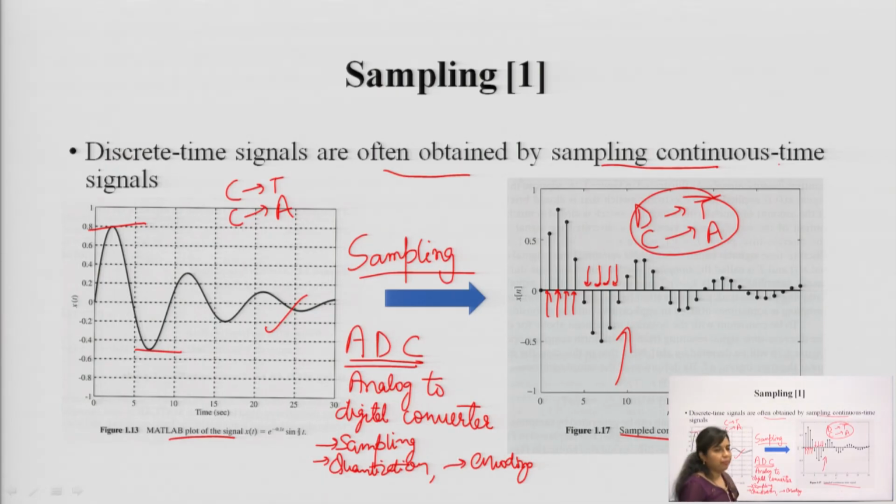Now, there are different types of samplers available, like the sample and hold circuit. Natural sampling, flat top sampling, and ideal sampling are some of the waveforms used to demonstrate the sampling signal. After sampling, this discrete in time, continuous amplitude signal is converted using quantization to a discrete in amplitude signal. This is how the discrete in time, discrete in amplitude signal looks with the use of quantization, and encoding will then be done, which converts it into 1-0 information.